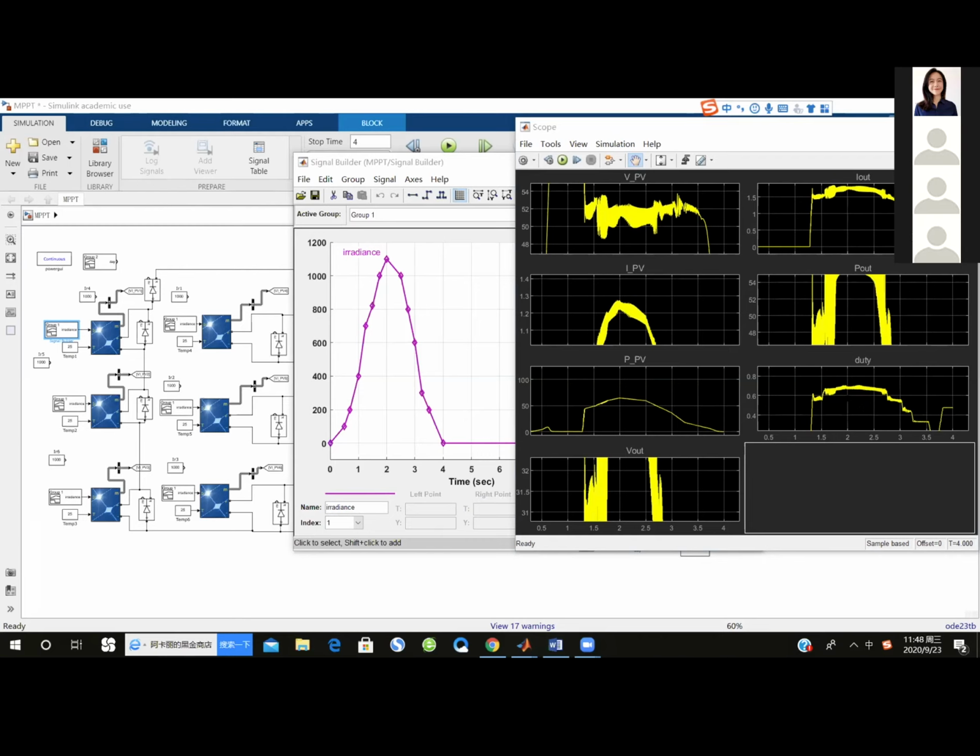And the second thing I can suggest is to track differently. When you are coding it, you are changing the duty from one side to another side, right? So change from the bigger number like 0.9, 0.95, and make it smaller. For example, when the true duty is 0.6, you track from 0.9 to 0.6 rather than from 0 to 0.6. Did you understand what I said?